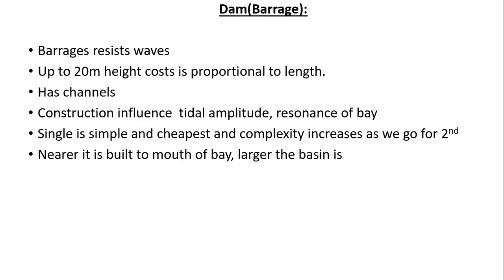Particularly if the scheme involves supplementary spur dams or brings about relocation or disappearance of natural obstructions, as is foreseen in several plans, this has occurred in Rance's case. This construction influences the resonance of the bay, and most bays are shorter than the resonant length of the tidal waves. If the resonance length is reduced, the range will decrease. So if measures are taken to augment the resonance, tidal amplitude will be increased.